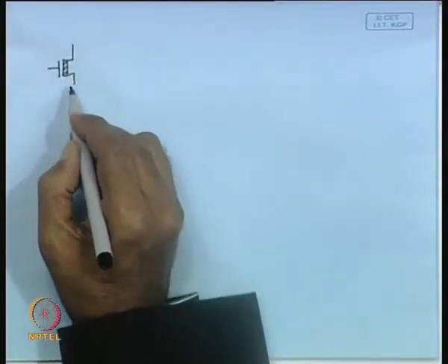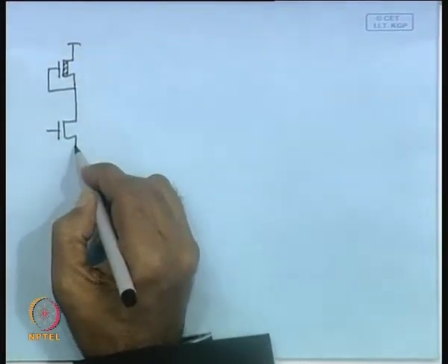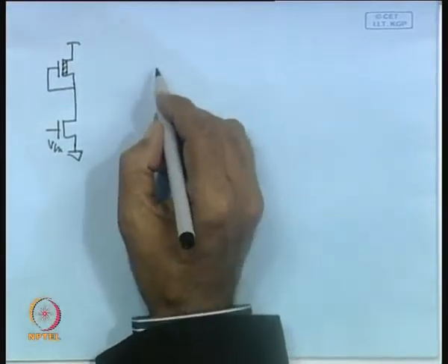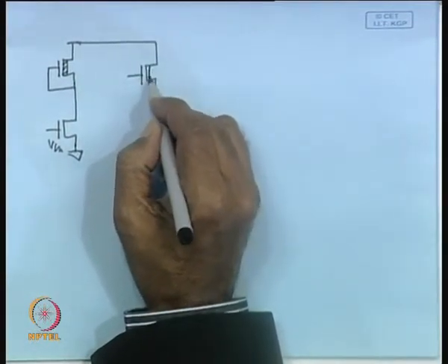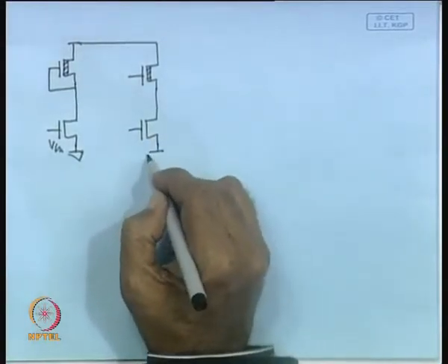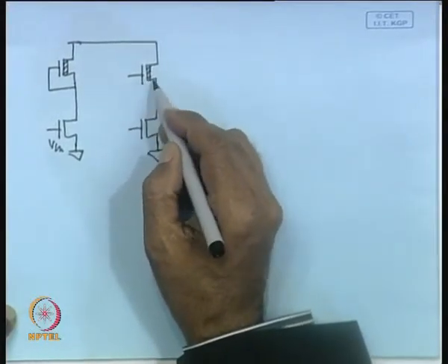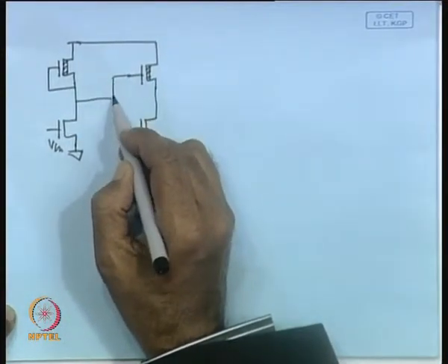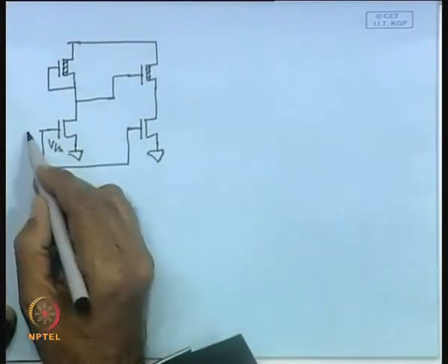So, as you know, this is a standard NMOS inverter. Here you apply the input voltage. We have used 2 more transistors, obviously one pull up and another pull down, but instead of connecting the gate of this NMOS depletion type transistor as usual, it is connected to the output of the first stage of the inverter, and then the input is applied directly to this.